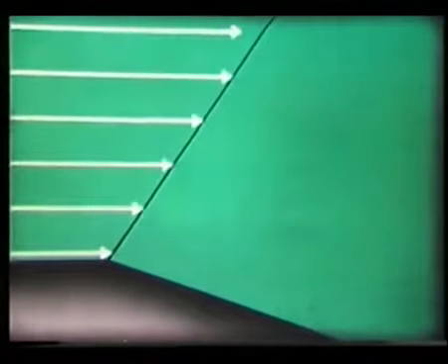None of the streamlines will be affected until they reach this Mach line. As soon as they pass it, they bend slightly and move further apart. The influence of the corner is at once felt along a new Mach line, and the streamlines bend again, and so on.